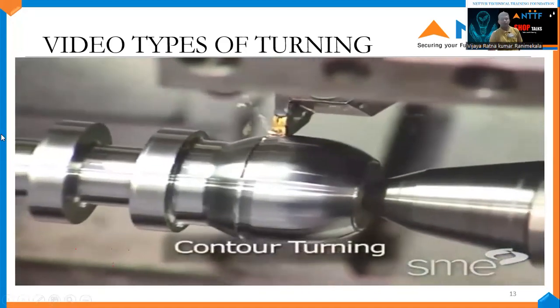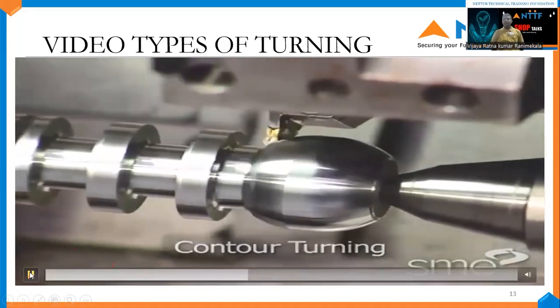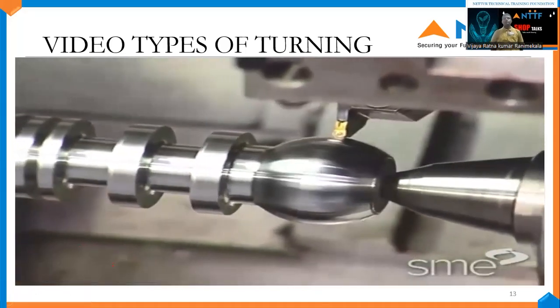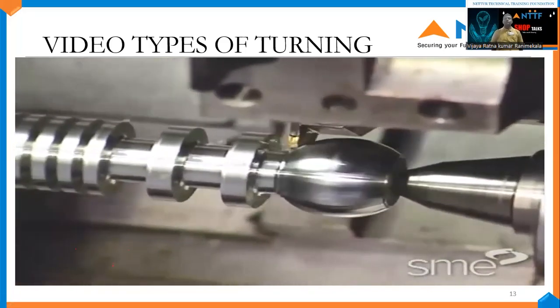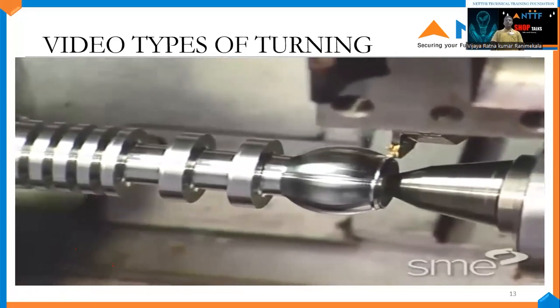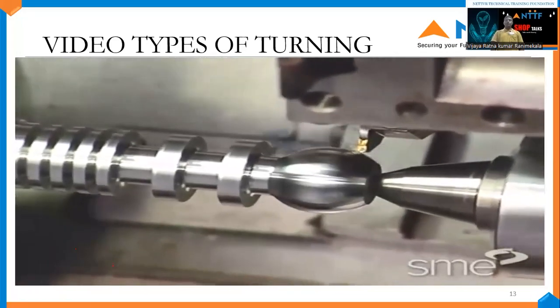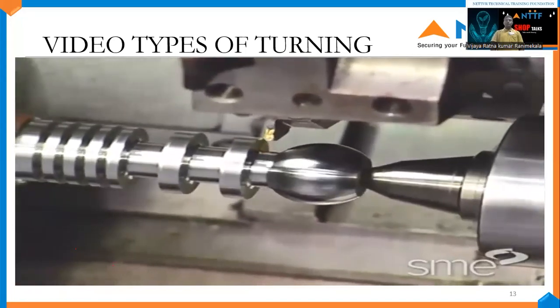Contour turning or profiling was formerly performed by having the single point cutting tool trace a template of the desired profile shape. This is contour turning. This has largely been replaced by CNC turning, in which the desired contour is simply programmed into the machine, which directs a cutting tool to cut the contour.